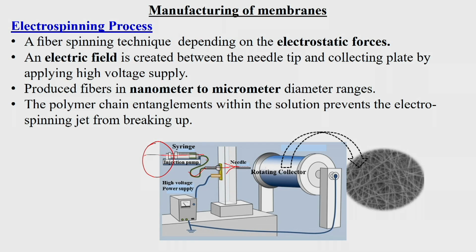and the needle of the syringe is made positively charged, and there is a rotating disc collector, rotating in either a clockwise or anti-clockwise direction. The needle moves from one side of the rotating disc collector to the other side, and at the same time the rotating disc collector rotates, either clockwise or anti-clockwise.